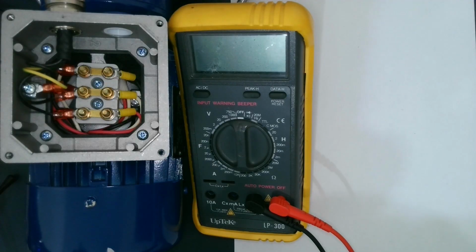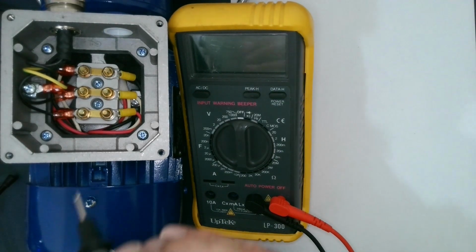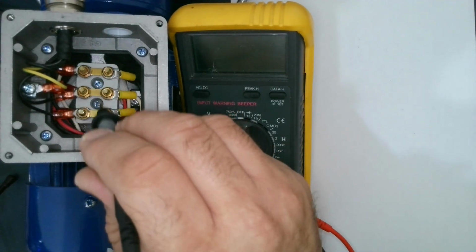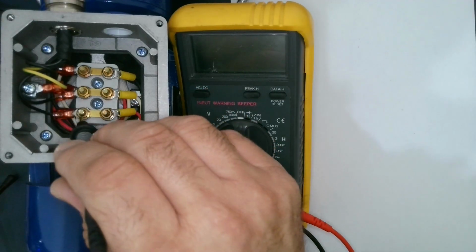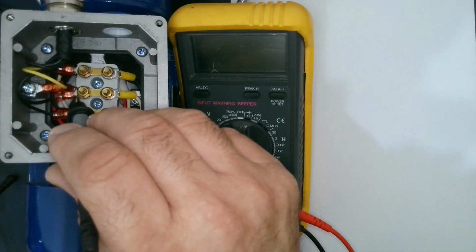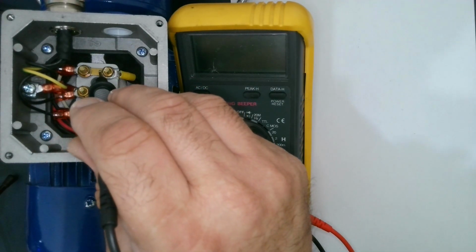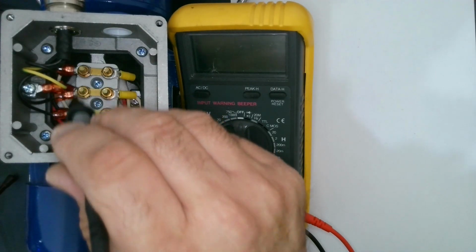Let's have another machine. The previous machine was star connected, or we measured between the phase and the neutral point, or the return of the phase. So here we have delta connection. We have 6 terminals, 1, 2, 3, 4, 5, 6. We connected start by finish, start by finish, start by finish. So we can measure between two of the points here.